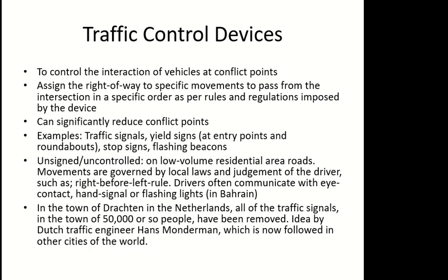And then we have other intersections which have so little movement, so less traffic that we can use them without any control device. The volume on that intersection is throughout the day very low. I'm not talking about low in a few hours of the day, I'm talking about low most of the day, 22, 23 hours of the day. Then we can take a chance that we leave it without the traffic control device.